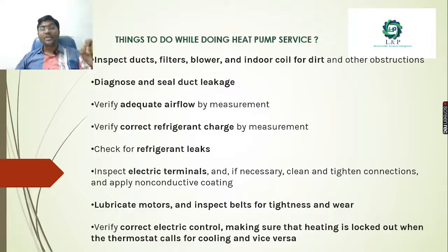We also need to check if there are any leakages in the refrigerants, and check whether the electrical terminals are properly connected. We need to inspect them properly, and check whether they are clean and tightened properly. Also, inside this there are many motors and belts, which can face wear and tear, so we need to lubricate those motors for smooth functioning. And we need to verify the electrical control, making sure heating is locked out when the thermostat calls for cooling.